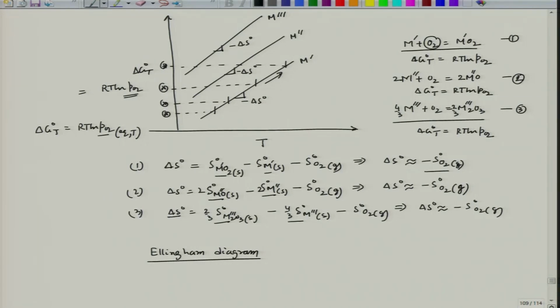There is one more way to calculate. If you see the Ellingham diagram, we will see that on the side, the right and the bottom side, there are some partial pressure of oxygen lines, and if we continue those lines, we find that they meet the delta G 0 T axis at 0 when T equal to 0 Kelvin. So, that is one way, graphically, to find out the partial pressure of oxygen in equilibrium at a particular temperature of consideration for any oxidation of metal.